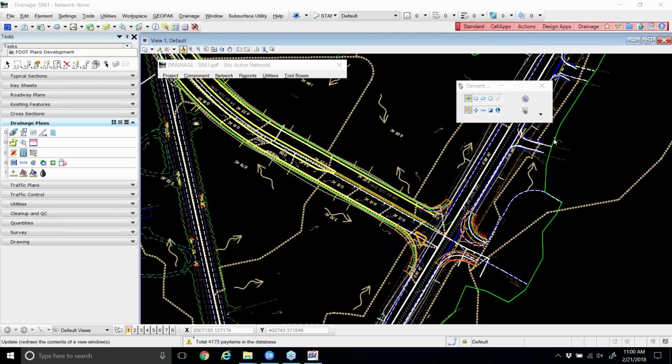So we didn't need the bottom of 416. We did not need the top of page 417. So we went straight to step 7, which we had already done. We had reopened our GEOPAK drainage project, and we had loaded the preferences.